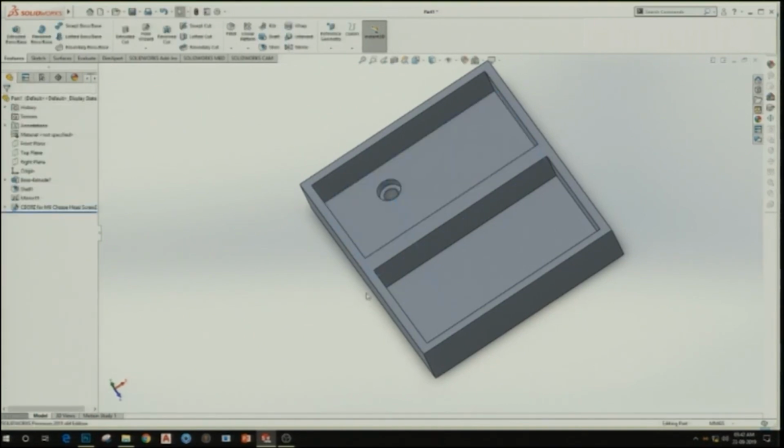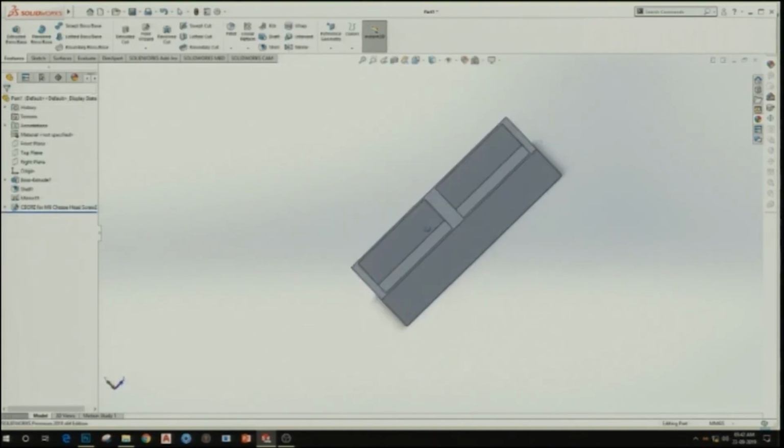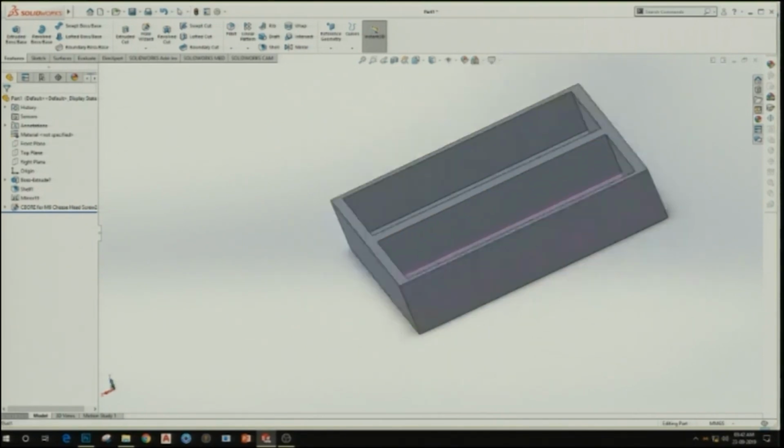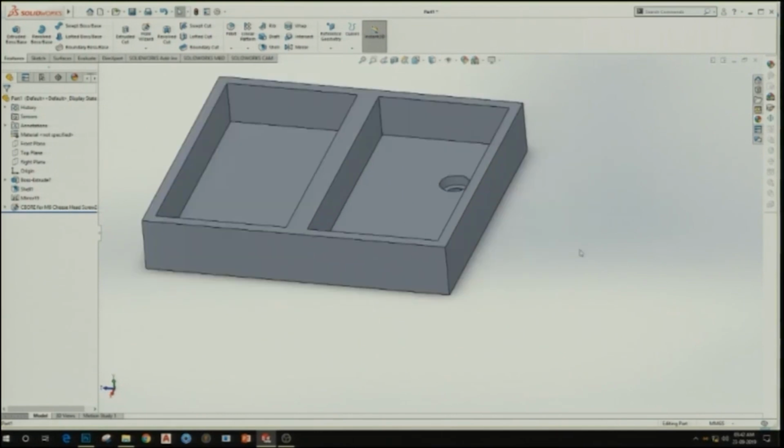If I select it here, it has made a hole, that is a counter bore, a hole and then a boring over it. It is generally used to make space for the screw or the bolt that we use over it. In this case it would be a screw. For bolting we have to have a spanner. So, this is also an important thing.